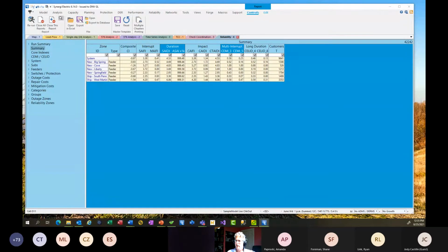The only time the load profiles get modified is when I was talking about the load profile at the meter. If you run that 576 analysis, there's a setting in there that says adjust my meter load profiles to account for generation. And that's when it does that processing to add the generation back onto the load profile. But that's only for the second approach, where you have your profile set up at the meter. If you're using customer class curves and things like that, those are all going to be very solid, because they're based on your load research data and so on.